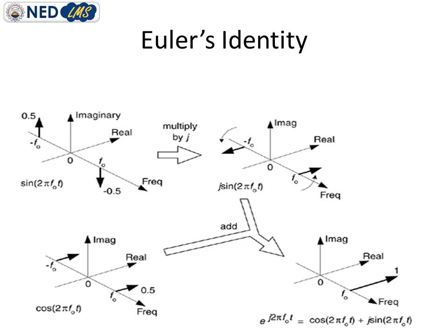So you can see that this is the actual frequency domain representation of sine wave, and after multiplying it with j, these two phasors are actually shifted counterclockwise by 90-degree. This phasor, which is parallel to the y-axis or imaginary axis, is now converted into a phasor which is parallel to the real axis, as it is the 90-degree phase shift.